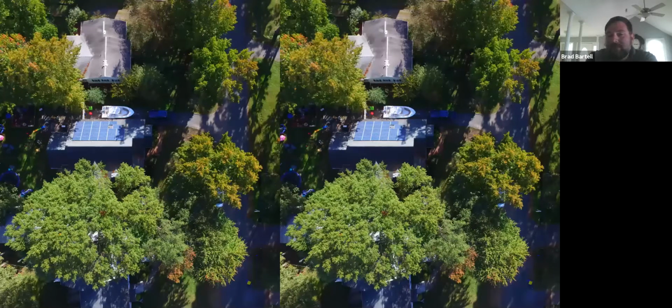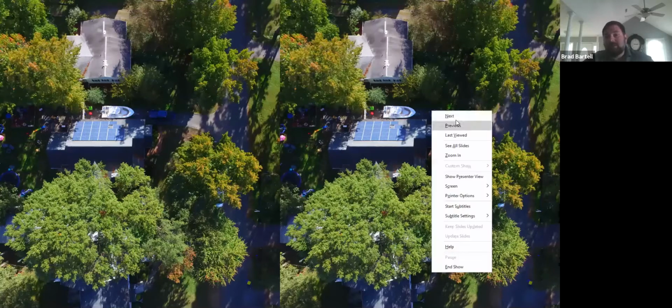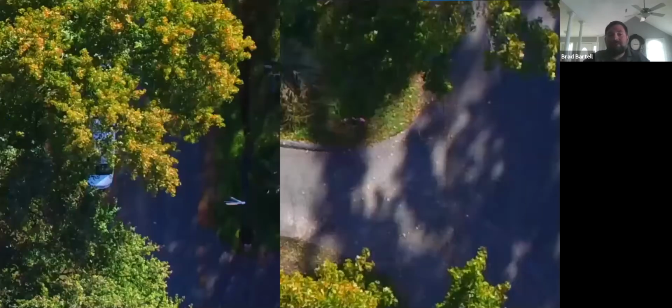So basically with the photo drone, everyone's used to panel points. The panel points are set with 2 GPS points down here. Once you fly over them, you make sure you have them in. And then when you bring it into the software, you just stick those where they're supposed to be. From that far, you can see there's a red chalk line on the top of the right screen pointing towards it. And if you look down on the left-hand side, in between the tree, right beside the white van, there's another panel point pointing towards the direction of where we're doing the flying.